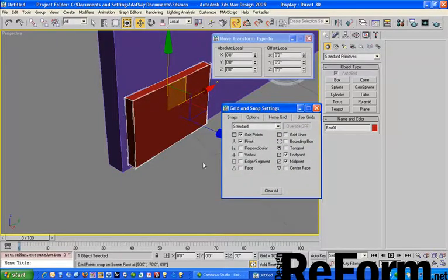So here you have grid points, which snaps to the grid in Max like this, which to be honest I don't use. I think most people do use it, but I tend not to, because I try to model based off the geometry and make construction geometry when I need it. Pivot point is based on the pivot. Perpendicular, I wish worked better, but that's the idea, it works perpendicular. You can snap and move things perpendicularly. Vertex is to a vertice. Edge or segment is anywhere, see, on an edge or on a segment. It's kind of like nearest in Rhino. Face is on a face.